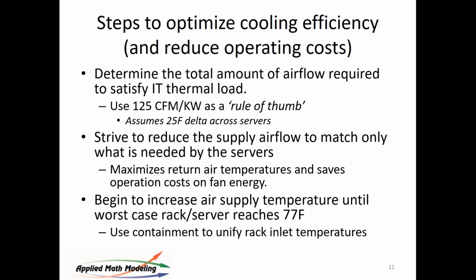So what you do is strive to get the airflow where you need it first, and then begin looking at supply temps. How high can I drive my supply temp? Now, the actual ASHRAE spec is 80.4 F before there's any issue, but 77 has become kind of the de facto standard for thermostats to begin to drive up the fan speeds on the servers themselves. So we use 77 to be a little bit conservative.